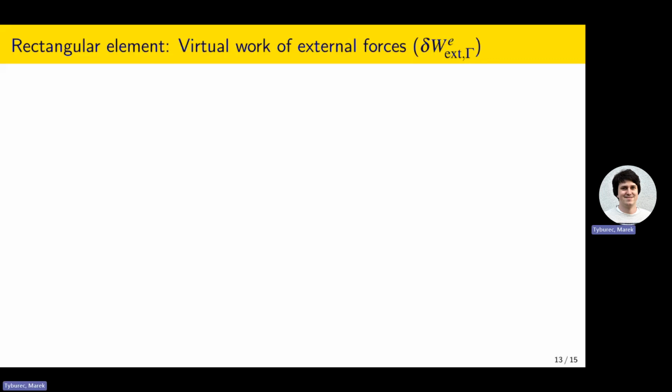So we say, okay, if that guy will be approximately the shape function matrix of the element, again a function of x, multiplied by some virtual node displacement d. And from that, what we get, again, this is something that is constant, so we can put it in front of the integral.